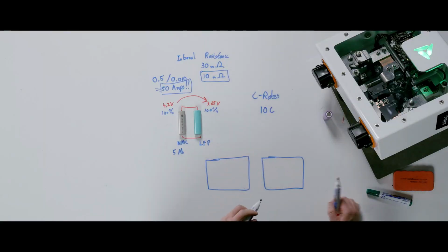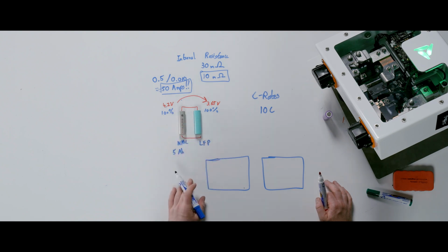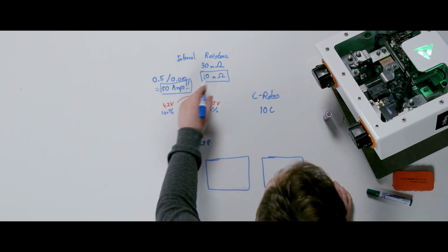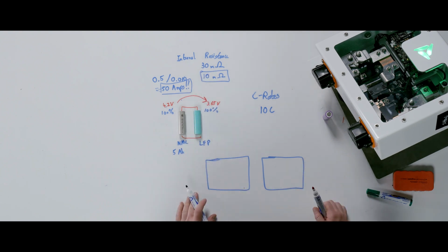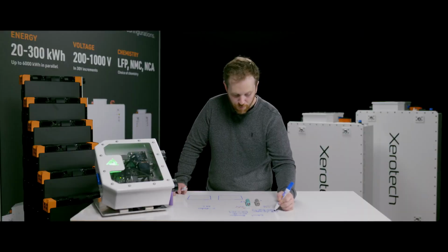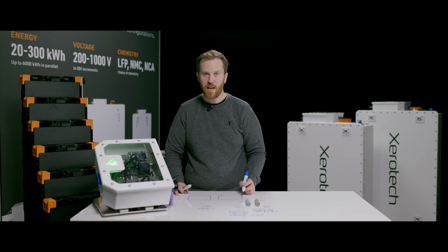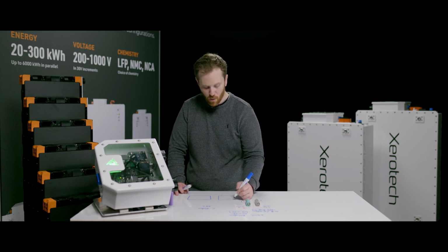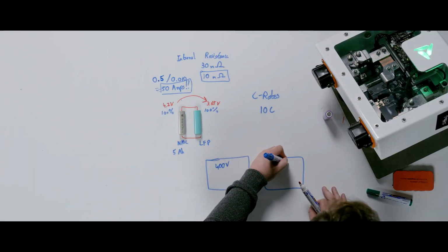And in fact, if you have an entire battery pack, it's even more dangerous, because you've got thousands, if not tens of thousands of battery cells in parallel. And this resistance is very low. 10 milliohms could be the resistance of an entire pack. And as opposed to having 500 millivolts or 0.5 volts of potential difference, imagine connecting two 800 volt packs together, and one of them was nearly empty, that 400 volts. And this one had 600 volts.